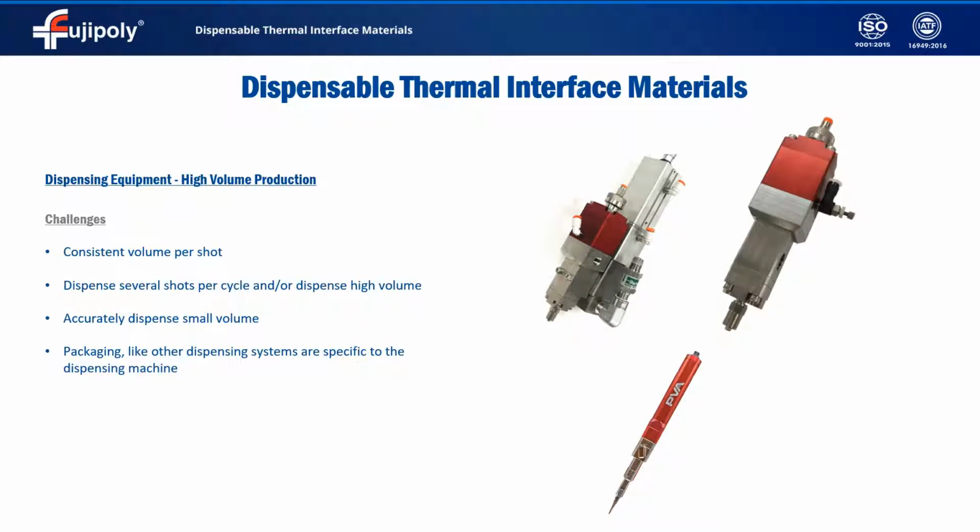So you could either have a fixed volume chamber that will be dispensed, that you couldn't adjust the volume of material being dispensed on the fly, or you could have a positive displacement, almost like a screw type dispenser. But again, the maximum volume and the flow rate will be limited compared to the pass-through snuffback valve.